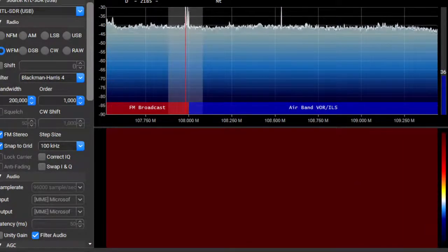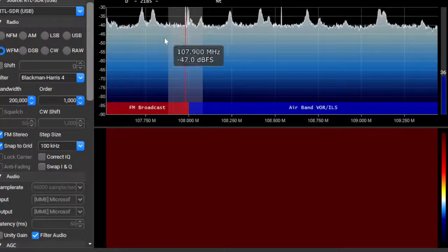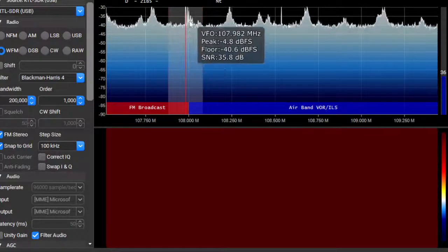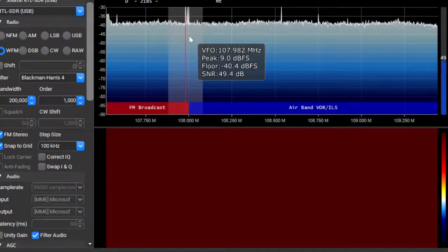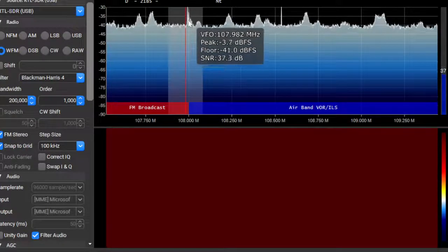Yeah, so what you see on your screen now is the software defined radio. We're using this to pick up the signal from our transmitter that we just built, the crystal transmitter. And right there where you see my cursor, or where you see the red line, is where the signal is. So when I turn off the radio, I'm just going to remove the power. You can see the signal just gradually vanishes away from this spot.